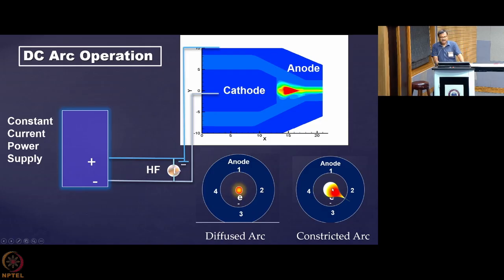But there are cases, especially at higher current, when you are passing a very high current through the gas, which ionizes the gas and forms a plasma. Then this current produces its own magnetic field, and that magnetic field, along with the current density J, gives a J cross B force which tries to pinch it. And this is a very flow driven region, because gas is coming from the top, from this blue zone, and they are disturbing, and there may be fluid dynamic instability.